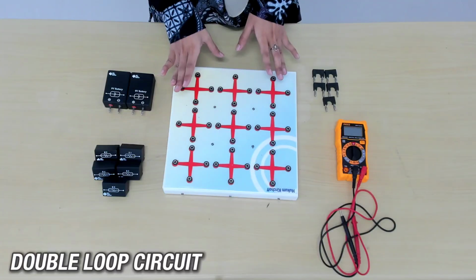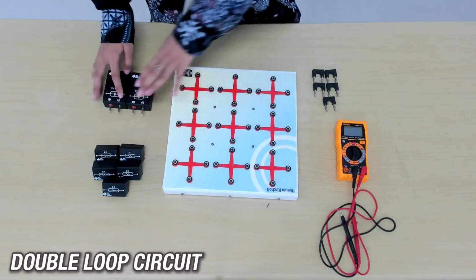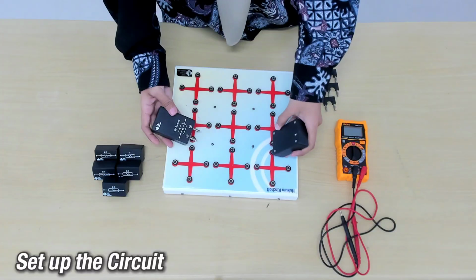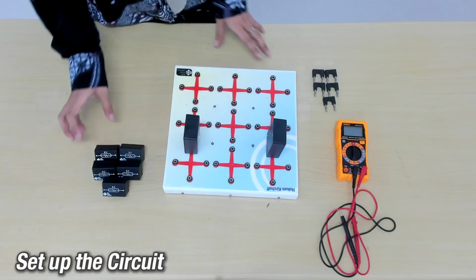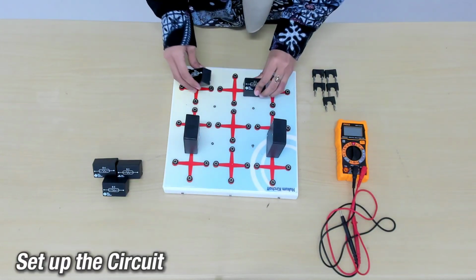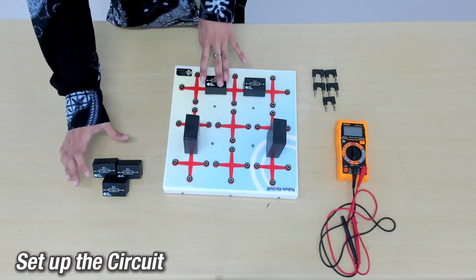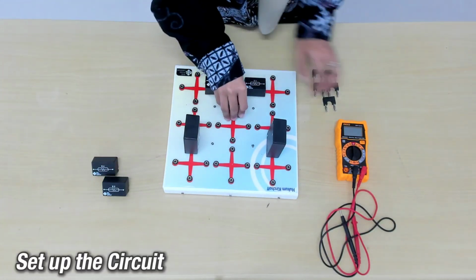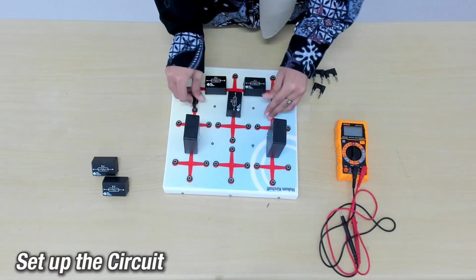Okay, now let's move on to the double loop circuit. For the double loop circuit, we will use 2 batteries and 3 resistors. First, take 2 batteries and insert them into the breadboard hole like this. Then take 3 resistors, which are R1, R2, and also R3. For R1, we place it into the breadboard like this, and here we use 5 connectors and attach them into the breadboard like this.